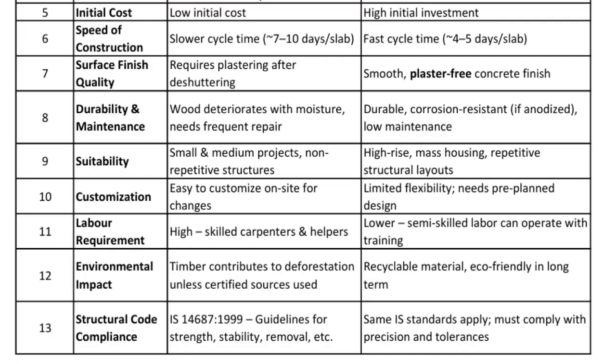Then customization. As I told you, the conventional formwork is easy to customize on site for changes. It is very useful if the structure is critical and the shape is non-linear. Then it is very important to use the conventional system because you can make it customized.